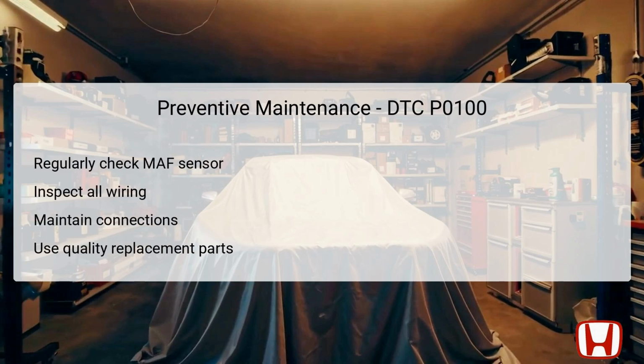Preventive maintenance serves as an effective approach to mitigate future occurrences of DTC P0100 and similar issues in the Honda CR-V. Regular inspections of the MAF sensor are essential. Clean the sensor periodically to ensure accurate readings and performance. Inspect electrical wiring associated with the MAF sensor for any signs of wear or damage.